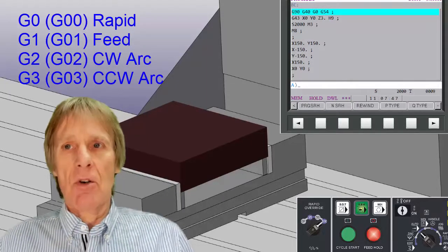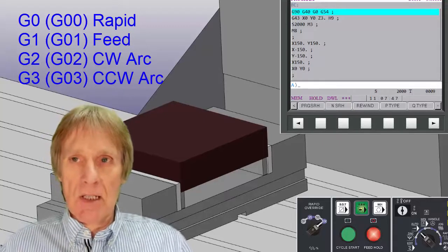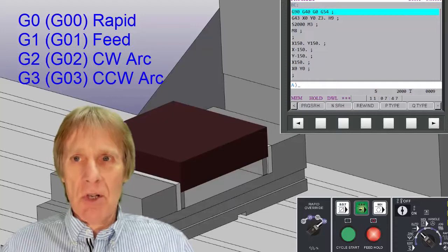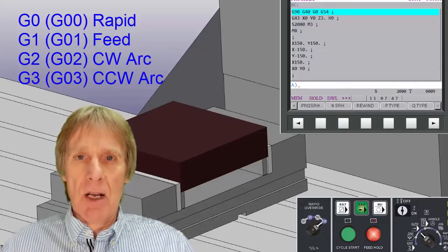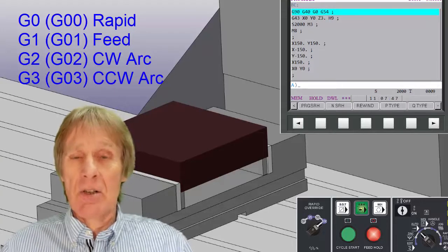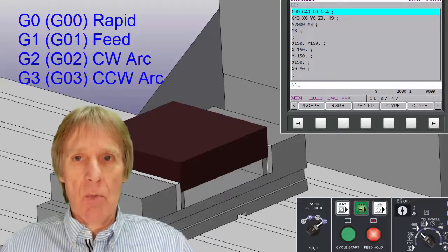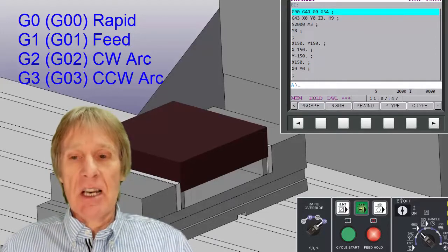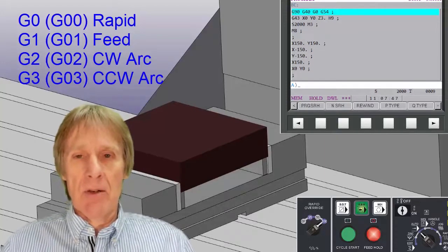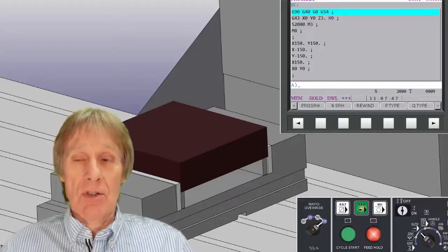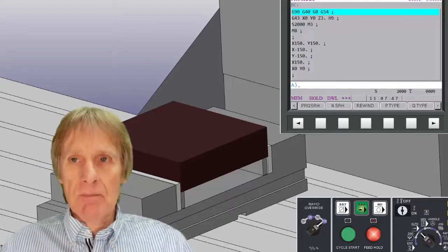Now, people will sometimes say G01, G00 or G02, and sometimes it's also known as G01 and G0, which is actually a misnomer. It's not actually correct. It's actually a 0. So, for example, G1 you can write as G01 or G1. I often say G01. It's just a habit I've got into, so you'll have to excuse me if occasionally I just drop that in, but it's actually wrong.